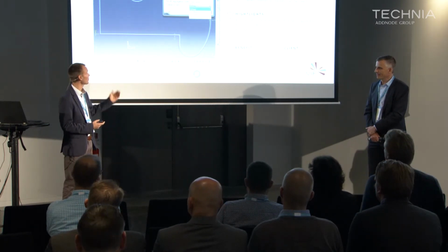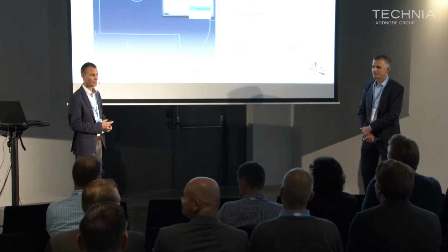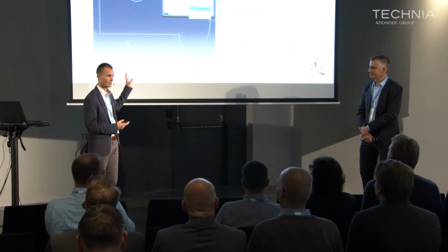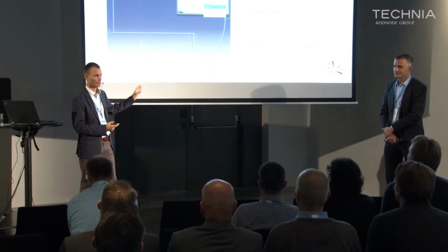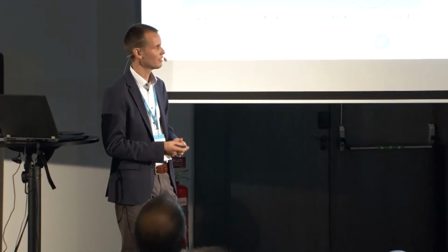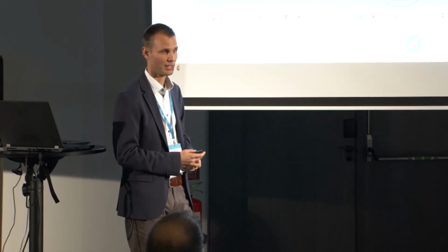So we started with the interface. Very easily, you select the contour, you select the tolerance class, and then it automatically creates the offsets, the inner and outer offsets. Saves time and resources of the customer, very beneficial in terms of automation. So here it's really about the creation of geometry inside of CATIA.